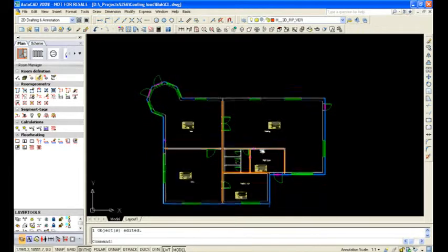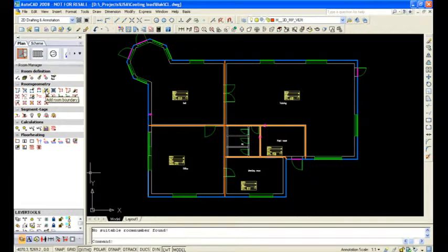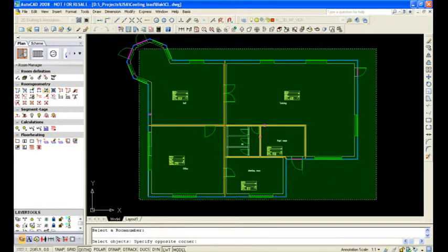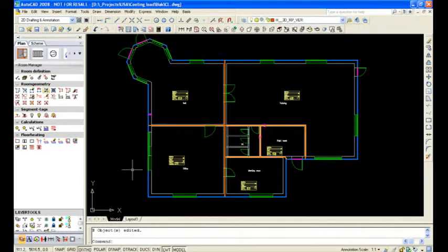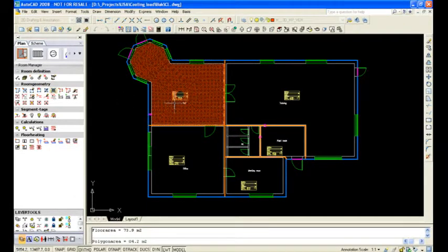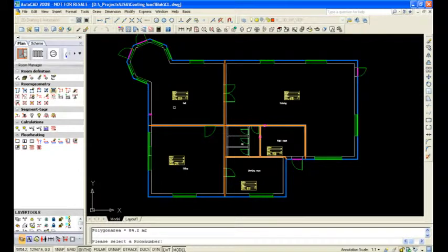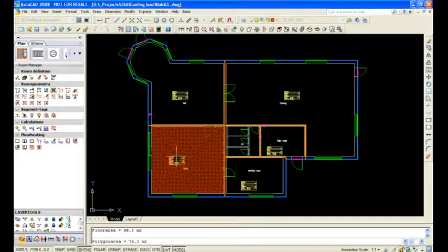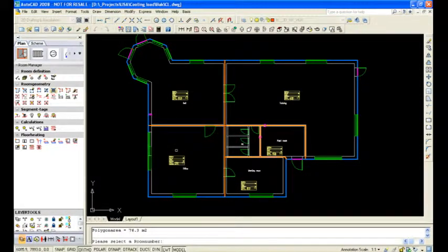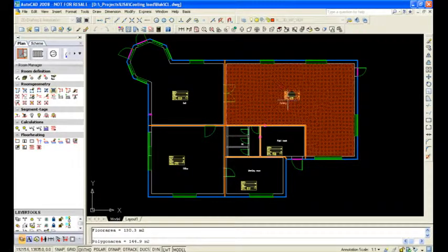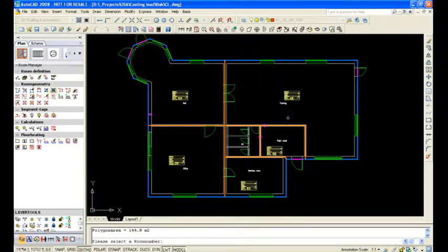We will assign the wall components to each room. We will highlight the entire drawing selecting all rooms. Now you have assigned the wall components. By clicking on one of the room numbers, you're able to see that the entire floor area changes color. This signifies that the room is ready to be calculated and has been assigned properly. Repeat the procedure for the other rooms.